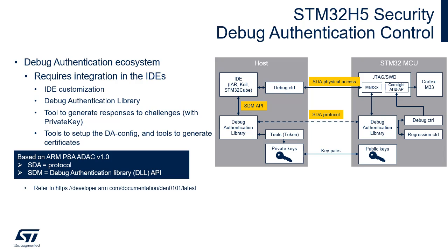It issues an authentication challenge and validates the credentials provided in response. Upon successful authentication, the SDA handles the hardware or software aspects of enabling debug access to target resources. In addition, upon request, it can provide the SDM with information about the debug target. This information can be used for discovery and identification purposes, to pass to the credential provider, to present the user with data to make an informed decision when choosing credentials, or other purposes.